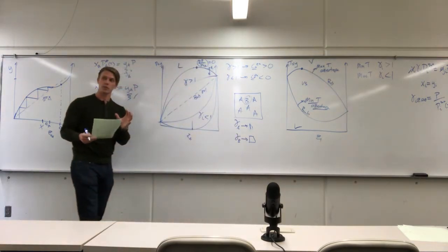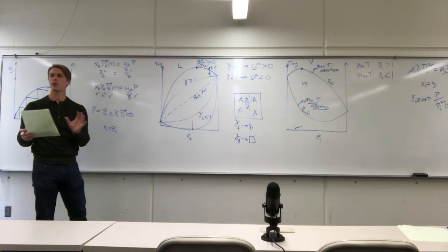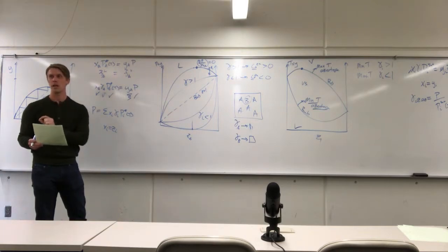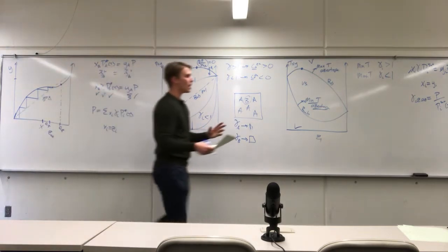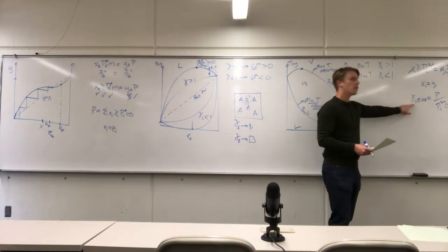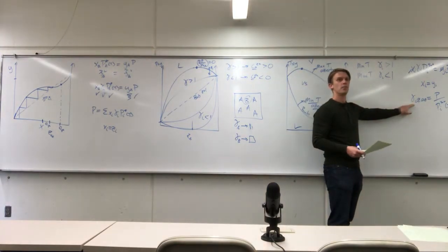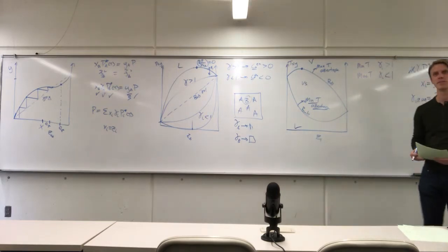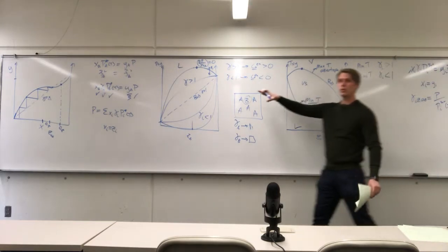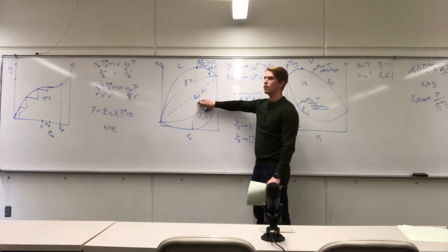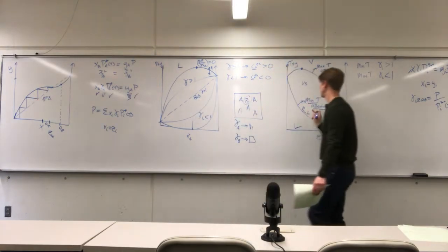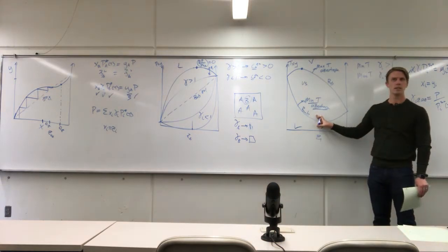But, okay, so here's the kicker. When I change the pressure, in thermo, all variables are connected to all other variables. So if I change the temperature, the properties change. If I change the pressure, the properties change. So by the letter of the law, my activity coefficient is also going to be a function of temperature, pressure, and composition. But the good news is that liquids really don't care about pressure changes that much. So the approximation that we use is that the activity coefficient isn't going to vary with pressure significantly. Whereas for the temperature, unfortunately, it does quite a lot.